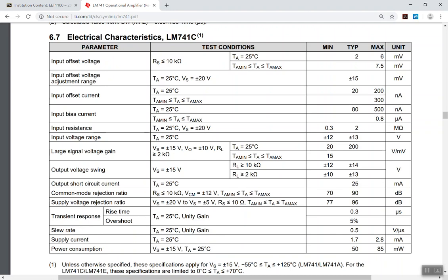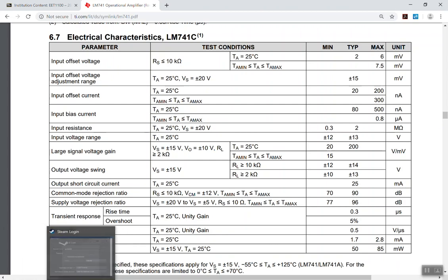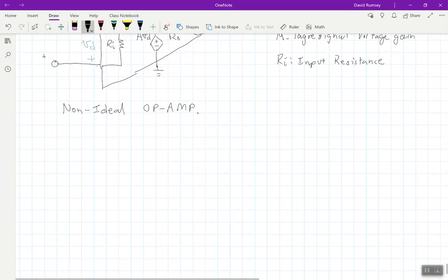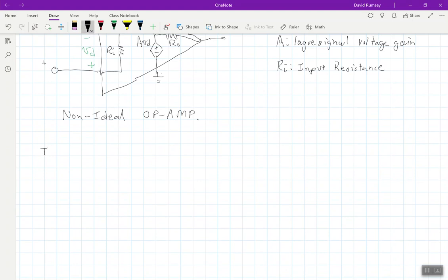Now for most of the applications we're going to do, in our lab and also in the lecture portion here, all of these things we're just going to assume are ideal, meaning that we have as high a slew rate as we need, it's as fast as we need it to be, we can put out as much current as we want, things of that nature. But clearly we can see those are not realistic when we're talking about real devices. But to have the basics of understanding these to start with, we start with just making life easy and assuming ideal situations. So our ideal op-amp here.